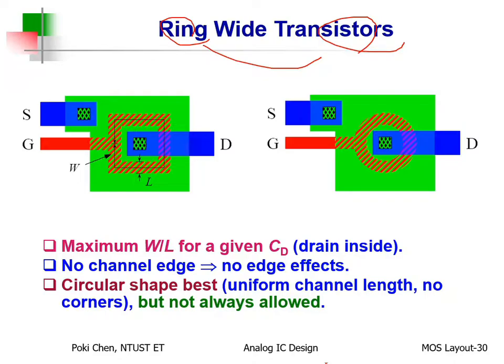Except for such very rare conditions, please don't touch it. Okay? It wouldn't provide you any kind of help. If you need such a very wide transistor, later I will share some better layout patterns for you. Alright? Don't touch this again unless for maybe an RF circuit, especially to drive an inductor.